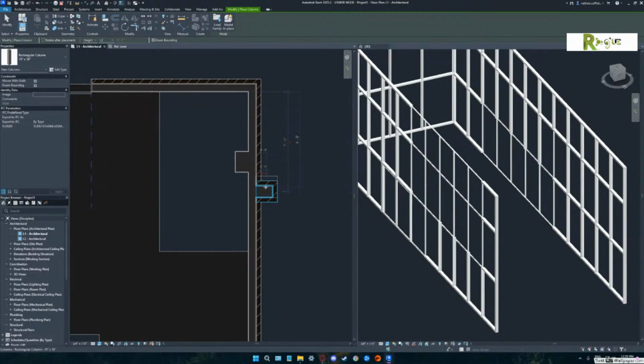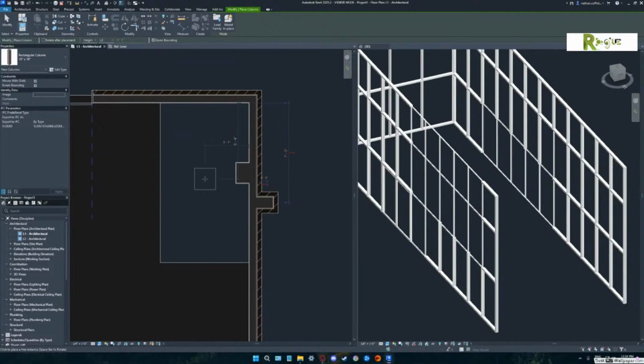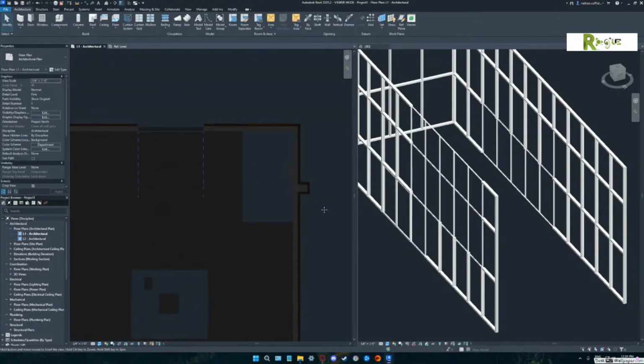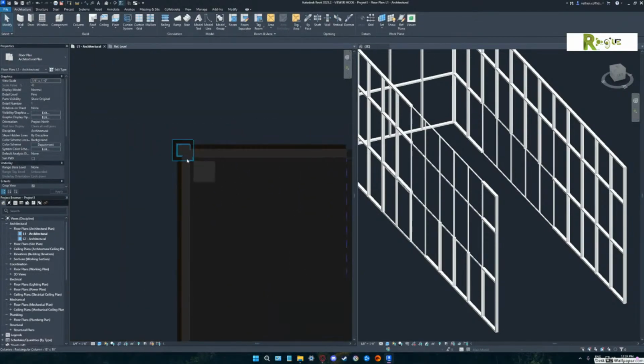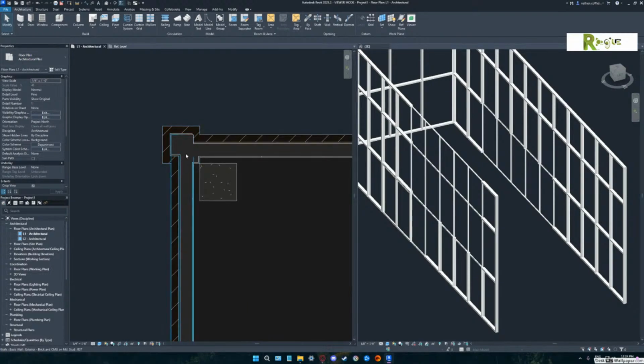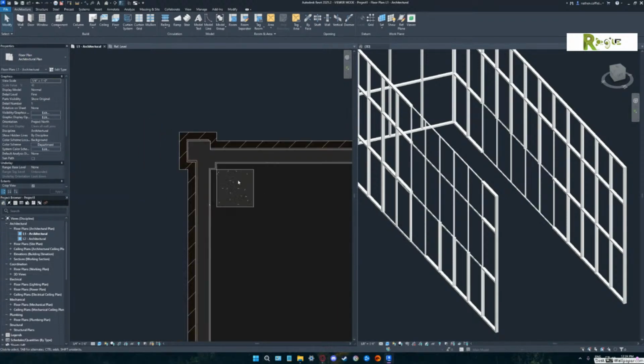Yeah. That also adds more pieces to the puzzle. It then also makes your floor try to wrap out there. It's one of those things that most people miss forever. I mean, I can go to people who've been using Revit for 6-7 years and they don't have an idea that is how that works. That's why I wanted to cover it. Okay. Yeah, that makes a lot more sense now. Because I understood over here how it had taken the form of the wall and it wrapped itself around. Yep. But I didn't know it would do that for specific parts.